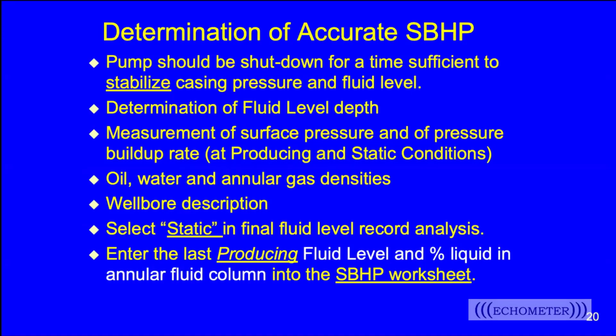We need an accurate determination of the fluid level. We need to measure the surface pressure and the pressure buildup rate at both the producing and the static conditions. And we'd like to know our oil, water, and our annular gas density. So knowing the fluid properties is good.